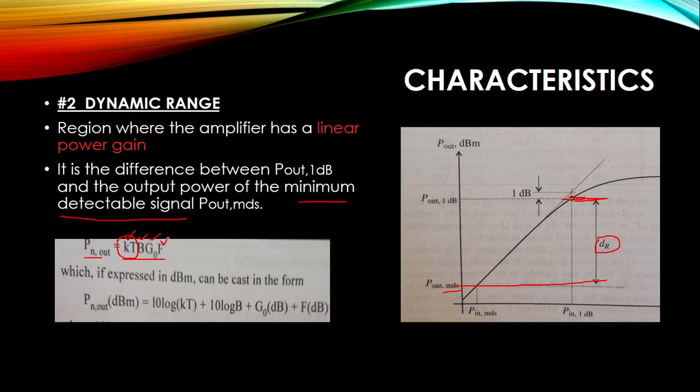It specifies the amount of noise that is added to the given signal by our device. Our device here is the amplifier. So how much noise the amplifier itself adds to the given signal is specified by a term called noise figure. If the noise figure number is larger, it means the noise present is more. If the noise figure number is very small, we can say that the amplification will be much more efficient.